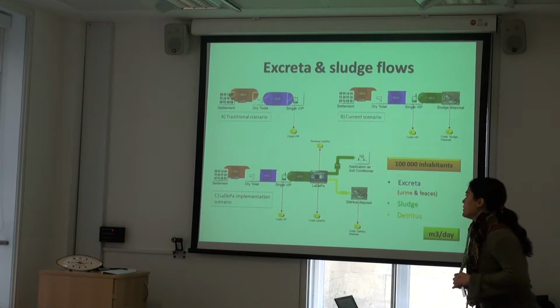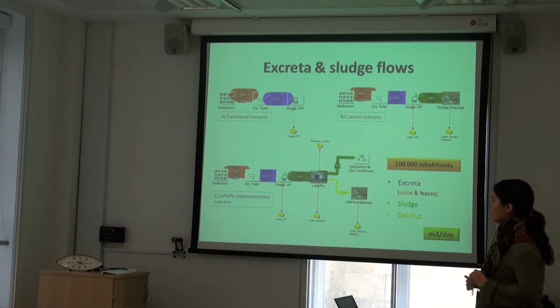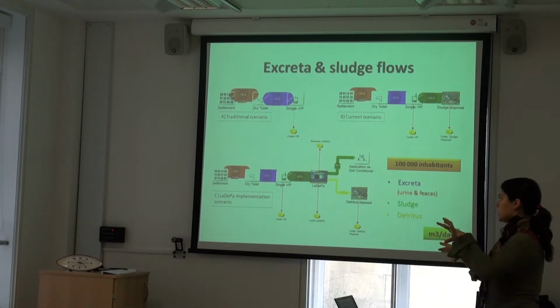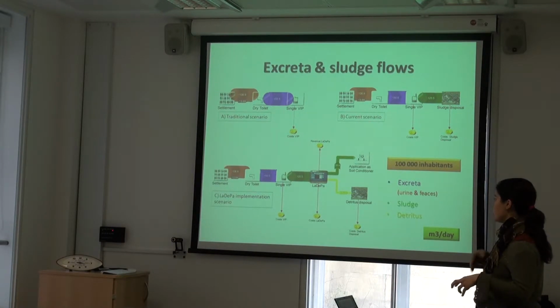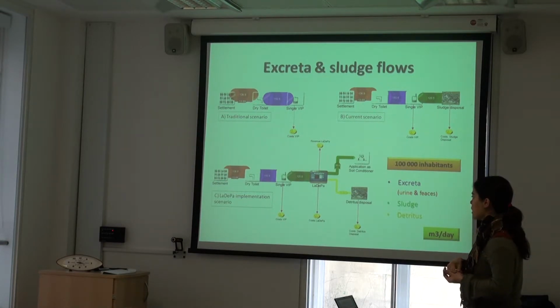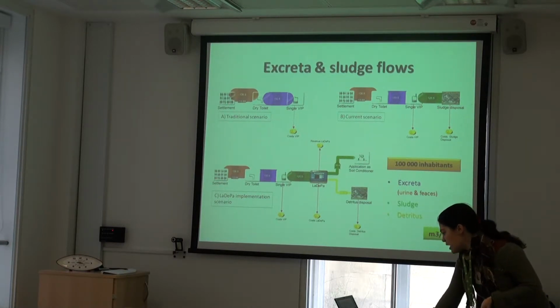But it's quite expensive, so obviously that one was the most economic alternative, but not the most environmentally friendly. And with the Ladeba, it was quite good. The idea was that on the one hand you separate what is rubbish from the sludge, and the sludge you heat up and reduce the solids so it can be used as soil conditioner, and the rubbish is disposed. So the amount of disposal is much, much lesser, and although the sludge soil conditioner didn't pay for the technology, through reducing sludge disposal, this alternative was more or less the same price as not doing anything with it, or in fact a bit cheaper, and much more environmentally friendly.